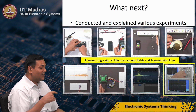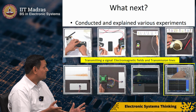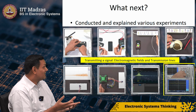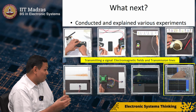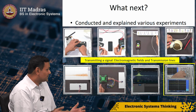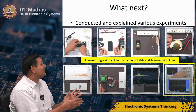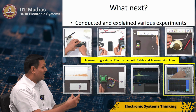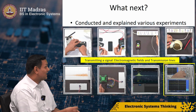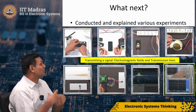And if you see modern computers, they're all running at gigahertz speeds, which means the time period is maybe hundreds of picoseconds to a maximum of a few nanoseconds. Which means the wavelengths are actually extremely small. So even a millimeter across one end of the IC to another can actually lead to delays. And these delays matter in processing signals.